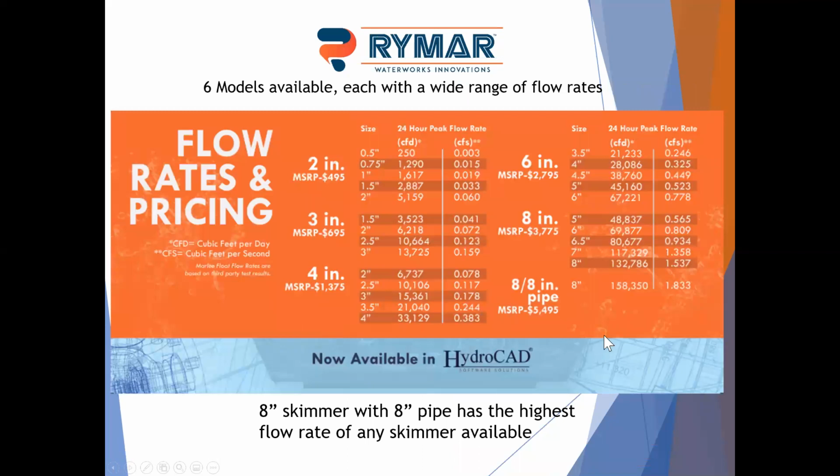We have 6 different models: our 2-inch, 3-inch, 4-inch, 6-inch, and 8-inch standard. And then we have what we call an 8-inch max, or 8-inch with 8-inch pipe. Our standard 8-inch skimmer uses a 6-inch pipe between the skimmer and the outlet, and we get very good flow rates with that. But if we jump it up to an 8-inch pipe for an 8-inch skimmer, we get almost 2 CFS of flow rate. So that really can move a lot of water. If you've got a very large site where you may have had to put in multiple skimmers, which gets a little bit complicated, you may want to consider our 8-inch with 8-inch pipe.